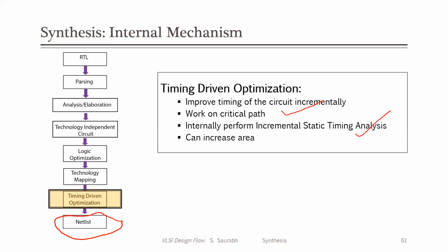Yes. Hello, sir. Sir, is the SDC file always given by the designer, or can it be generated using tools also? See, there are tools to generate an SDC file, but the tool will give you a template. The tool cannot infer what clock frequency you want to work with, right? So you have to fill in all those data in your template.